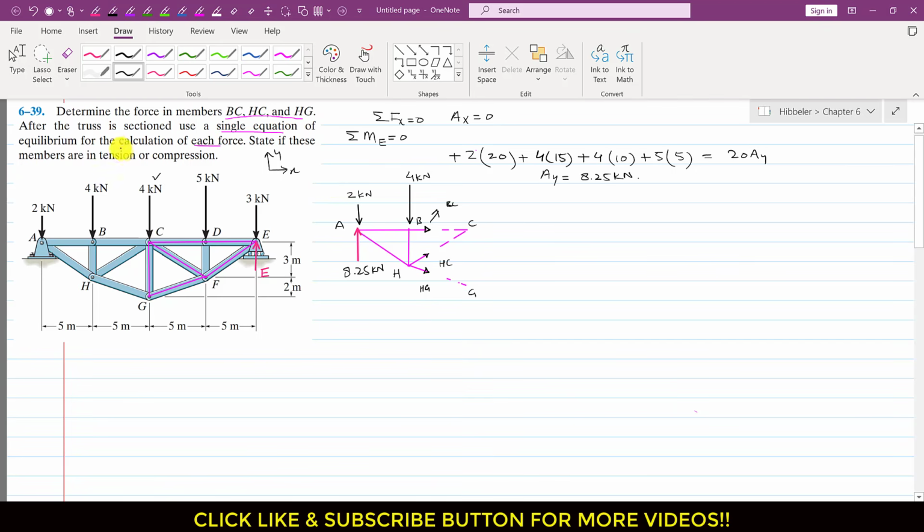Now, since we are asked to use a single equation, if I want to find this BC force, as we can see, the lines of action of this HC force and this HG force both pass through this point H. So if I apply the summation of moment about point H equals 0, then this HC and this HG will not come into our equation, right?